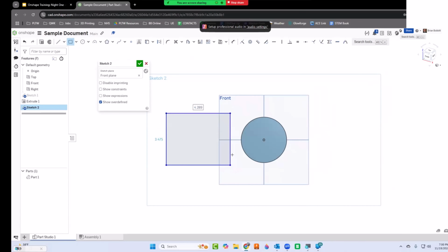Draw a rectangle. I want to kind of sneak in some sizes now. After I draw the shape, you notice that right up here, there's a number. And then also right over here, there's a number. If I just start typing, so I'm going to say, make that 5. And if I press enter, it'll take me over to the other side. You can say, you know what, make it 3. So to continue, I could hit the green check mark and it's going to change this menu at the top, right?